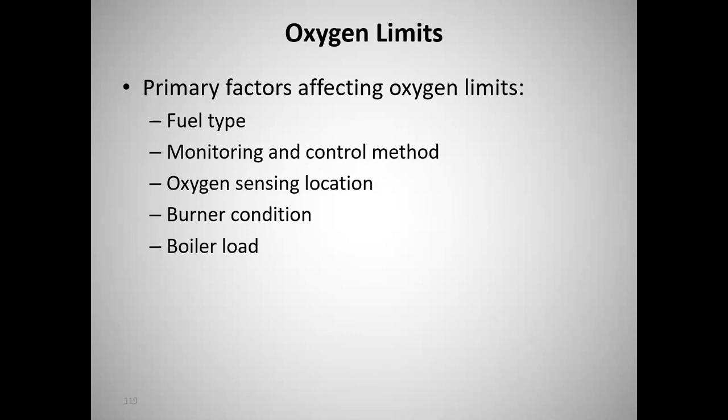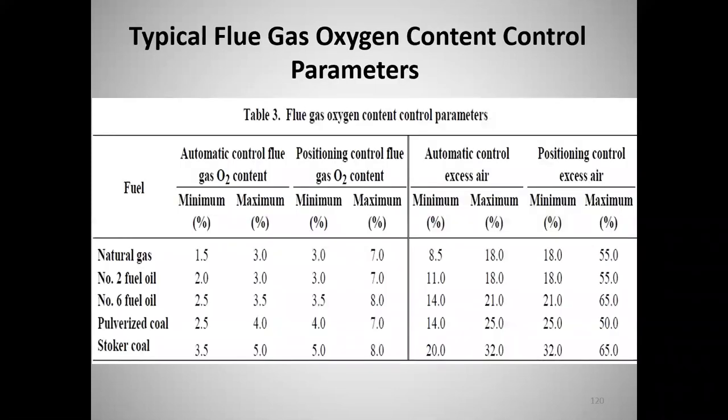Burner condition, certainly. We could have maintenance issues on a burner, and until you fix that, you're probably not going to be able to get very good control of your excess air. And boiler load affects the required oxygen level.